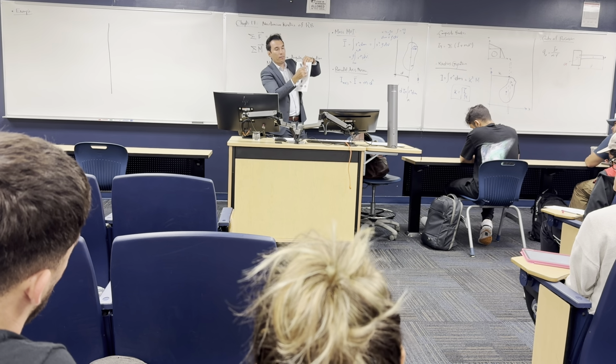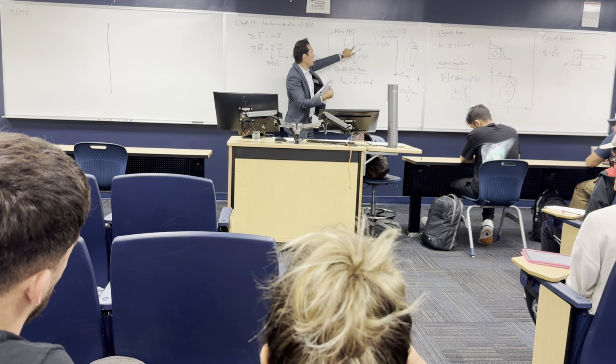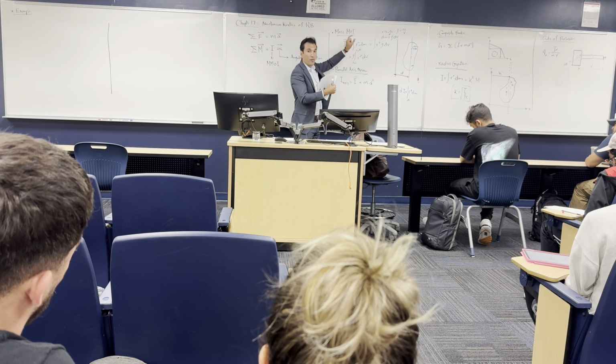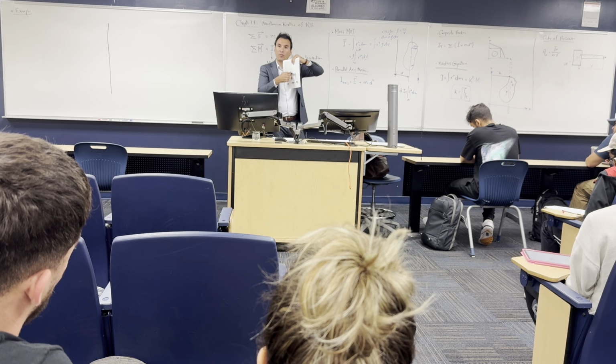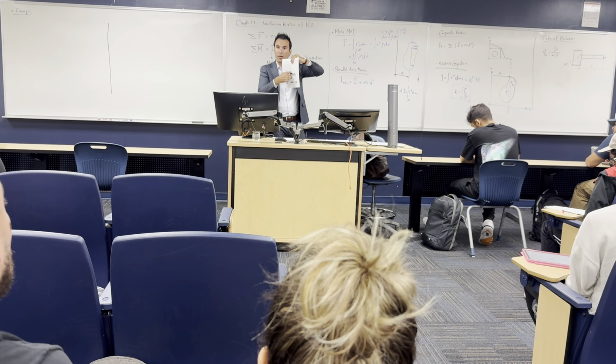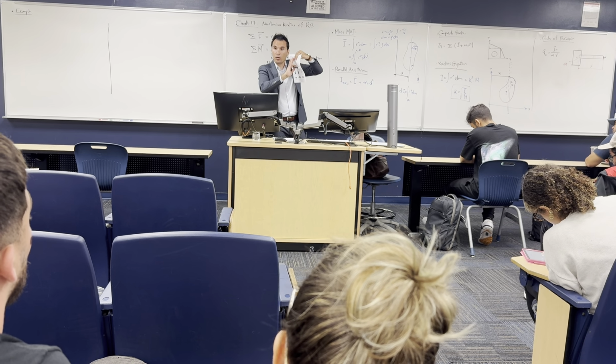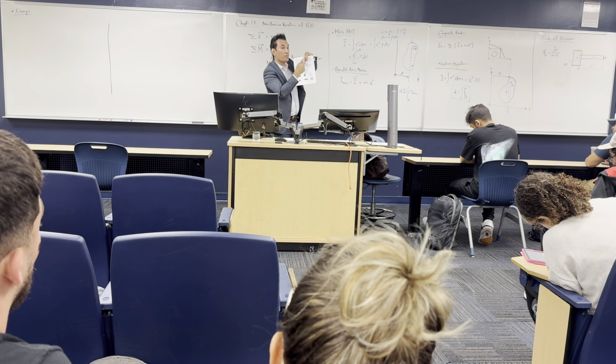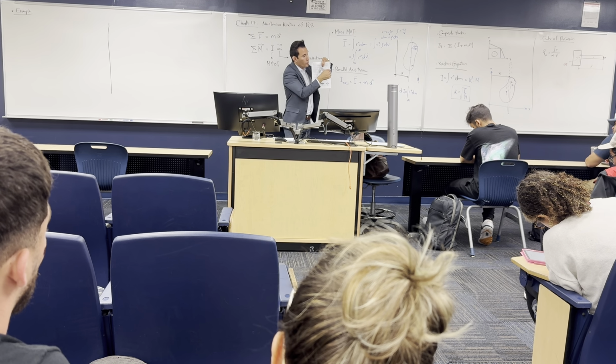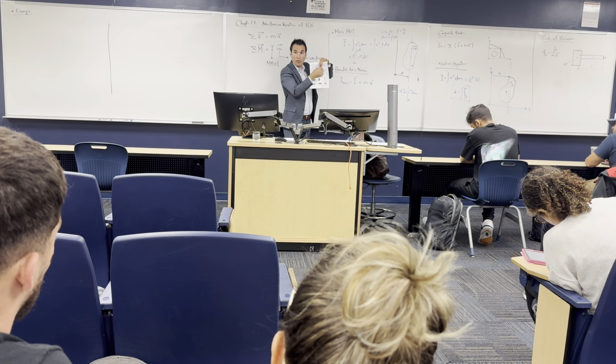So we measure r, the distance of the mass with respect to the axis that we get the moment of inertia about. So if I'm asking you the mass moment of inertia about x, r is measured from the x axis to the mass that you are looking at. If I'm asking about the mass moment of inertia about y, the mass is measured from y.